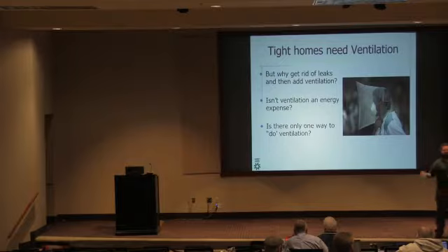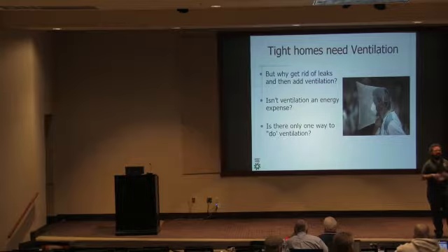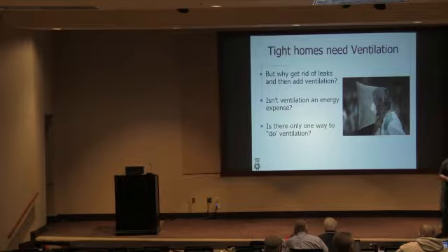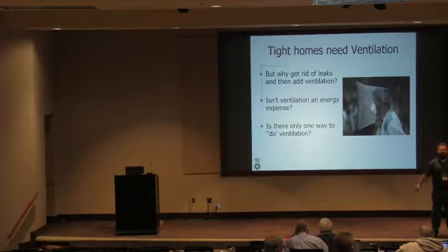And so if our house is always under negative pressure, then we always are pulling in outside air from somewhere. And if we don't get to choose where that outside air source is, then we don't know whether it's attic air, crawl space air, coming down our chimney air, who knows? Have you all seen this one? Somebody gets the big old giant hood range put in the kitchen, and now it blows like 1,200 CFM out of the house through their beautifully renovated kitchen. And then they call somebody out because they're like, my whole house smells like a chimney, what's going on here? You're like, oh, it's called makeup air, and your chimney is now providing it.